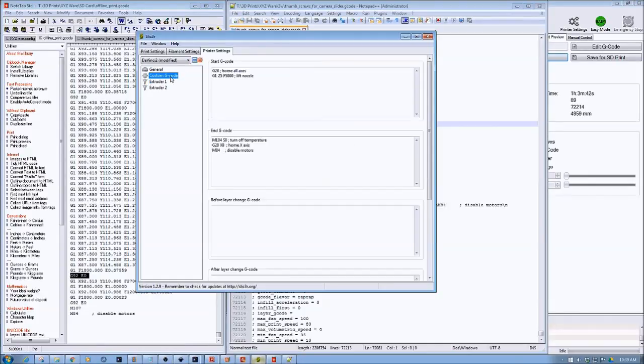be trying one head. However, what I wanted to show is this custom G-code. So you can put in a start G-code, you can put in an end G-code, and you can see here how the end G-code is coming up with this. And so one of the things that, if this all works out, I plan on doing is put my prefix G-code all in here and all my suffix G-code in here. And then when I slice it, I can just save it, and technically everything, or the majority, should be there, and I only have to do minor editing in